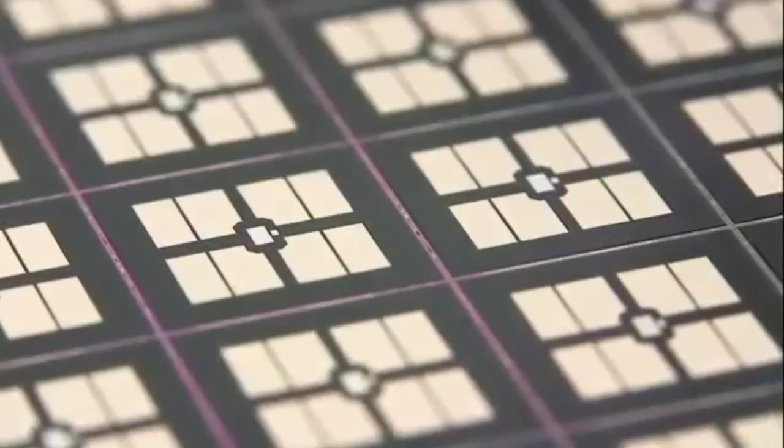Individual chips are usually sawed out of the wafer. The chips are not lined up flush with each other on the wafer because tiny parts of the wafer splinter off during the sawing process. A certain amount of space, known as the scribe line, is always left between the individual chips. Test structures are also integrated in the space between the chips and used to take measurements immediately after production. These test structures are destroyed during the sawing process. The size of the resulting chips typically varies between 1 square millimeter and a few square centimeters.